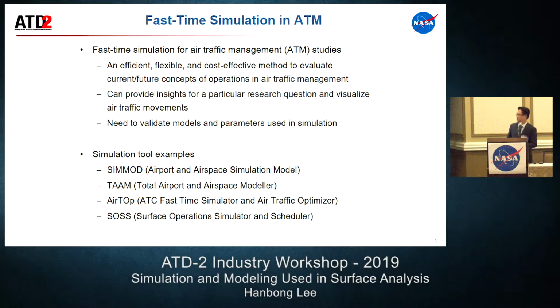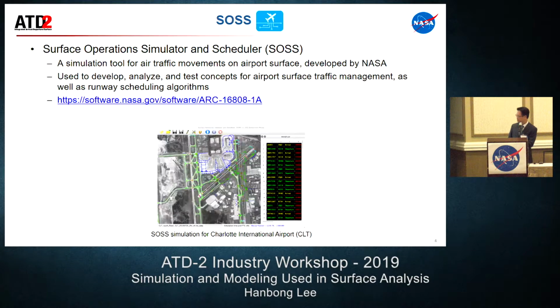There are lots of examples of phase-time simulation tools, including CMOD, TAAM, AirTop, and SOS. But today, I will focus on the last one, the SOS. SOS, the Surface Operation Simulator and Scheduler, was developed by NASA for airport surface operation modeling.